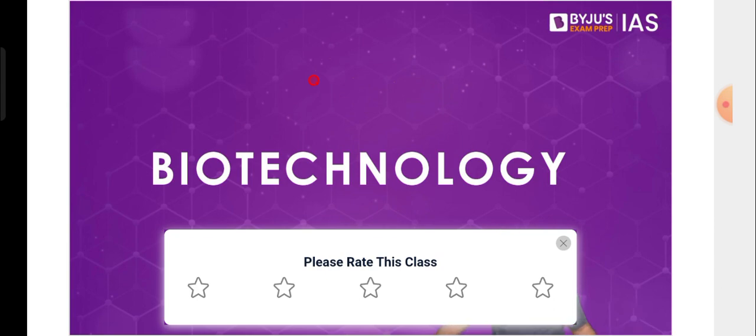Why is GSLV used in the Chandrayaan mission but PSLV is used in the Aditya L1 mission, even though the sun is farther? The basic structure is that if the satellite weight is less than 1500 kg, you can use PSLV. If it is beyond 1500 kg, you can't. Aditya L1 is 1400 something, correct? Chandrayaan 3 is 2200 something. A 2200 kg satellite can never be launched with the help of PSLV, but a 1400 kg satellite can be. That's why we use PSLV XL for Aditya L1, and we can't use PSLV XL for Chandrayaan 3, and hence we use GSLV Mark 3 there.